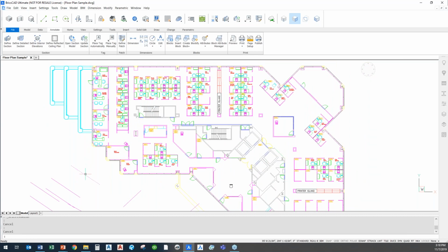Everything that I need in terms of editing and manipulation is all right here in the quad tool. I can change colors, I can change layers, I can change line types, I can change distances, lengths. And I also have the ability to pull these in and integrate these directly. I can add dimensions, I can do offsets. How far do you want to offset this? 5 feet, that easy. I can offset any object and then repeat the offset. Now go 5 feet the other way, okay?